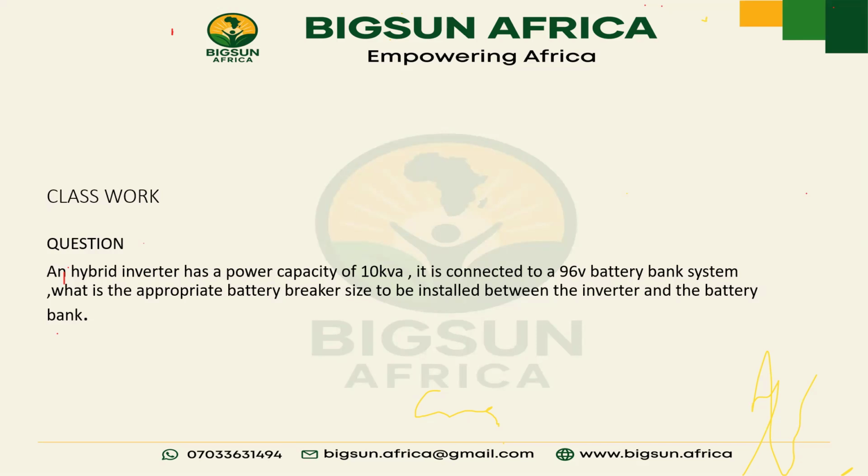Our breaker size calculation is going to be 8,000 times 1.25, which is equal to 10,000, then divided by our battery value, which is 96. So we have 104. Is it clear? Yes, clear.